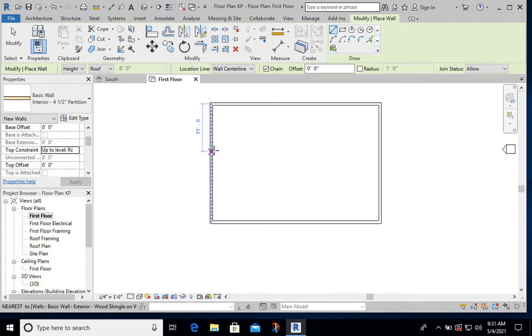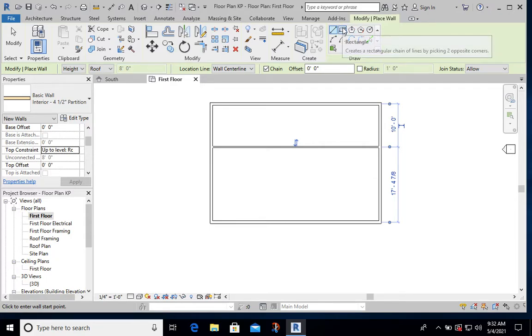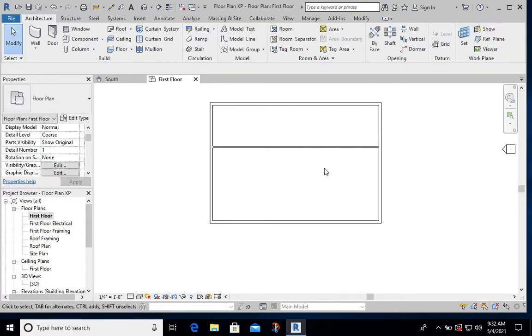And I'm going to draw in my first wall the same way we did on our line drawing. We're going to just come about 10 feet down. We're going to have to fix this, but about 10 feet. That draws one wall, so I clicked on that wall, straight over till it snapped to 90 degrees because I'm using my single line tool. If you're getting a rectangle, it's because you have the rectangle tool selected. If you need to go back, you have the back button here, and that will remove it.